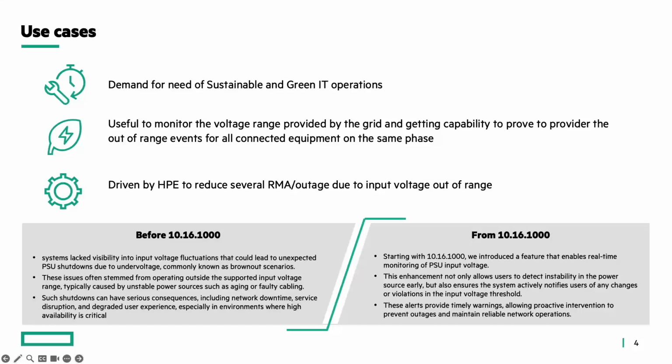Despite being rated at 100 or 110 to 240 volt nominal voltage range, Aruba PSUs are regulatory required to be able to operate 10% below their normal voltage, meaning 90 volts if rated at 100 volts. These values, plus or minus 10% above or below the nominal voltages, are referred to as the normal range. The PSUs are capable of operating beyond this normal voltage range.